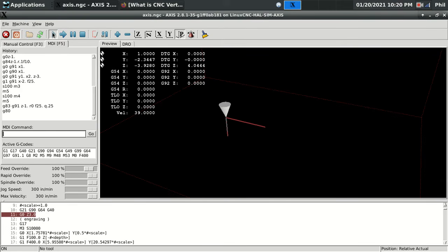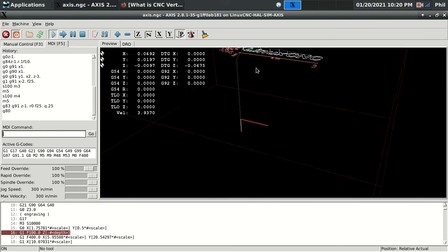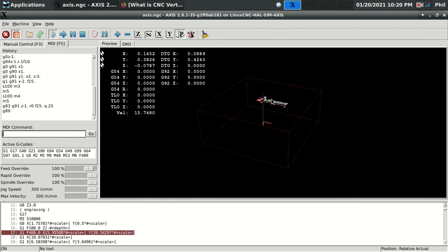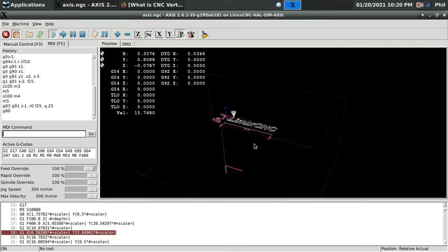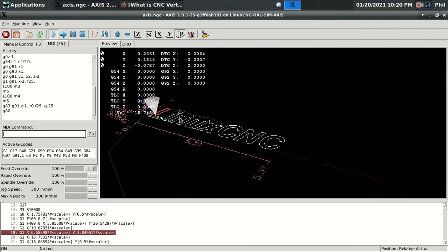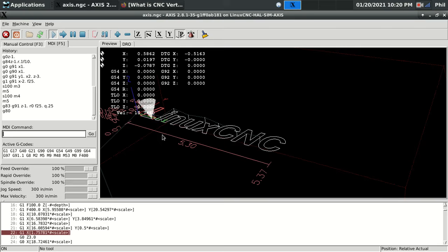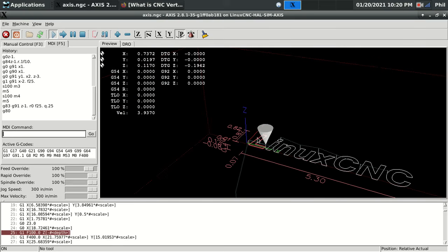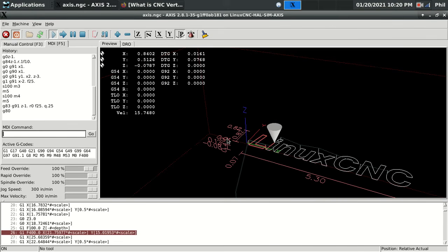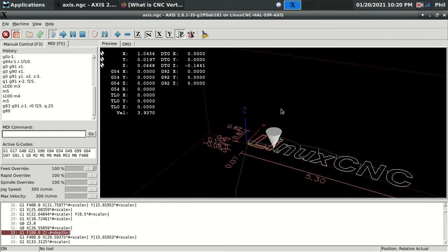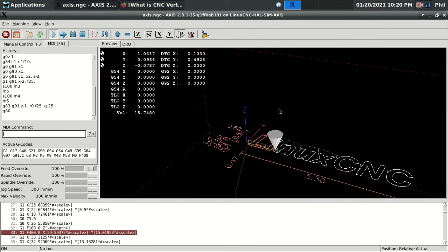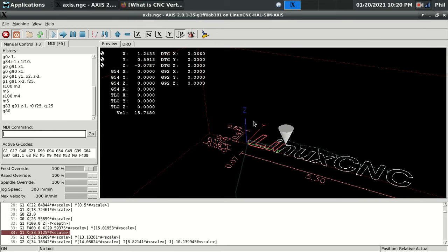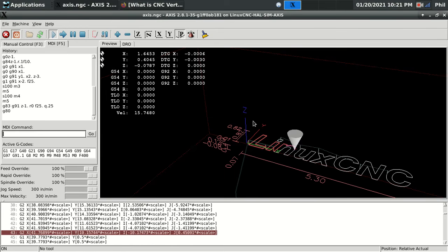When I press the play button, it puts the machine into auto mode, and it runs the program that's currently in the machine at the position that it has set for the work coordinate position. In this case, it's using machine home, but machine home is arbitrary depending on where the machine was when it was turned off and turned back on, because this simulation environment doesn't have actual home switches.